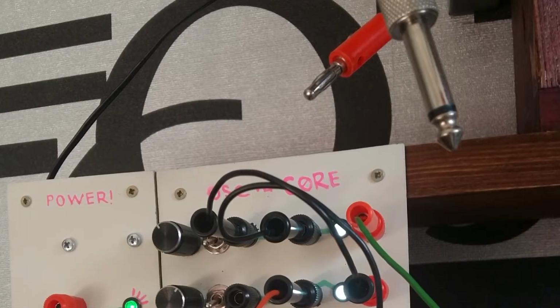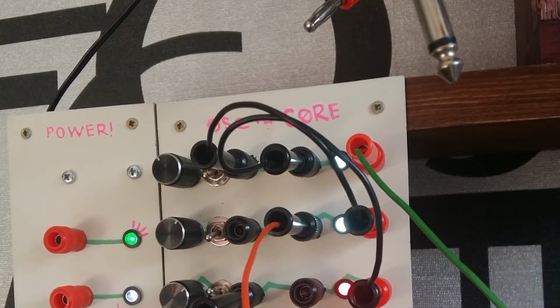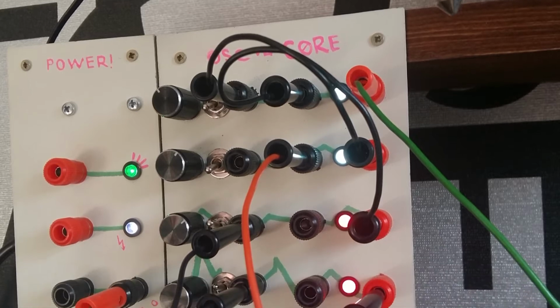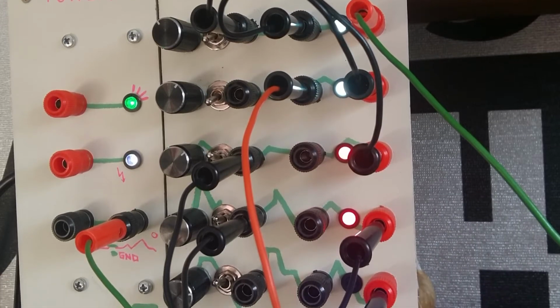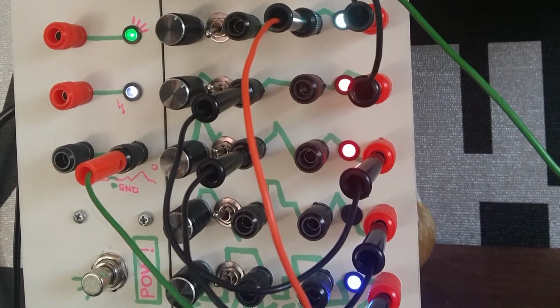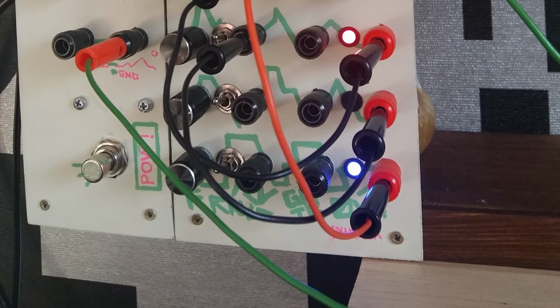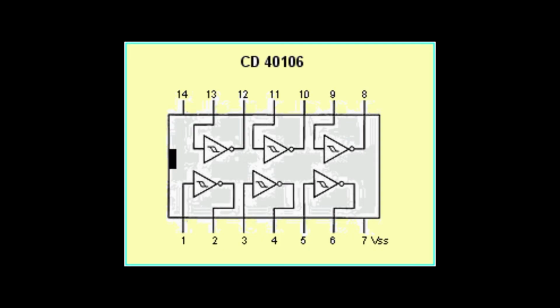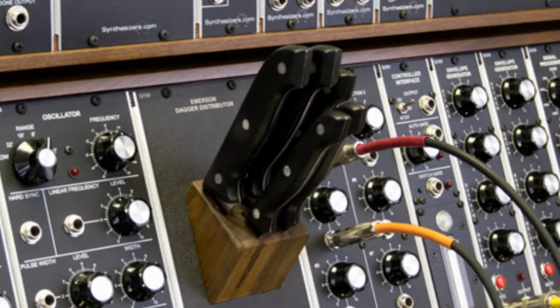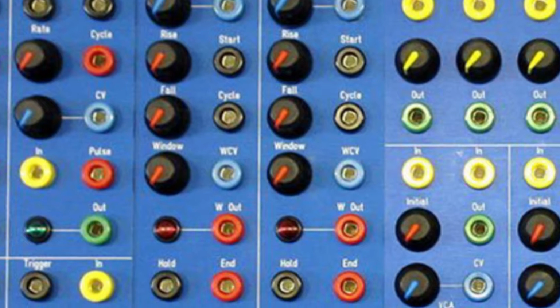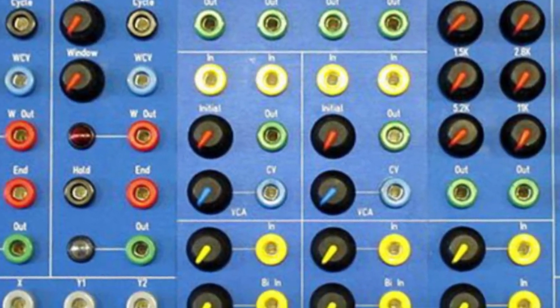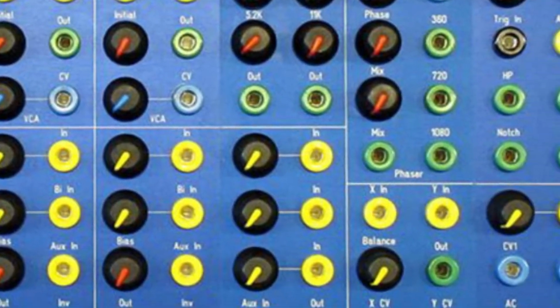In the last episode, we made a module which has 6 square wave oscillators that are voltage controllable and hard gateable. They are pretty good for generating some glitchy textures and so on and so forth, but are not enough for our system for sure. Moreover, the ICs we used in them are CMOS logic ICs, which are generally considered as digital. And today we're gonna do something very analog, which means that it won't generate just zeros and ones, like our square wave oscillators do, but instead will give us desired smooth curves and slopes.